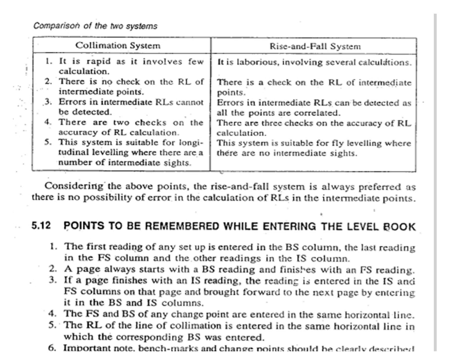The first reading of any setup is entered in the BS column, the last reading in the FS column, and other readings in the IS column. Second point: a page starts with a BS reading and finishes with an FS reading. If a page finishes with an IS reading, the reading is entered in the IS and FS column on that page and brought forward to the next page by entering it in the BS and IS column.